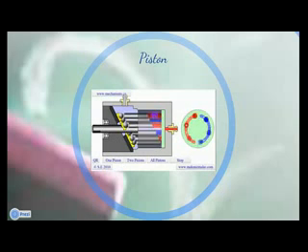After a cylinder reaches its furthest point from the port plate, the cylinder passes the gap between the crescents and the compression cycle starts. Let's see how two pistons operate. Notice that during compression, the piston passes in front of the shaft, and while replenishing with fresh oil, the piston passes behind the shaft. This was done to show the 3D visualization of the pump.